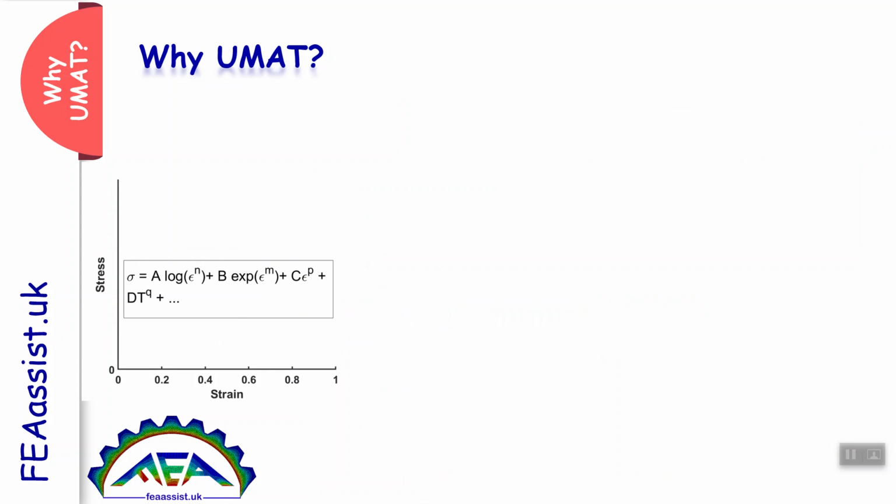But consider you have a new material or a new constitutive equation. The equation between stress and the components is very new, which is not included in Abaqus, and you don't have points. So what can you do? Then you need a place to write this equation or your equations and tell Abaqus to obey this behavior to solve my problem.